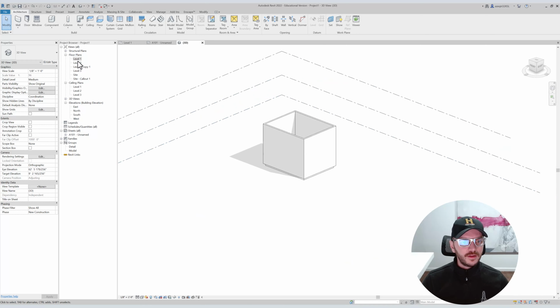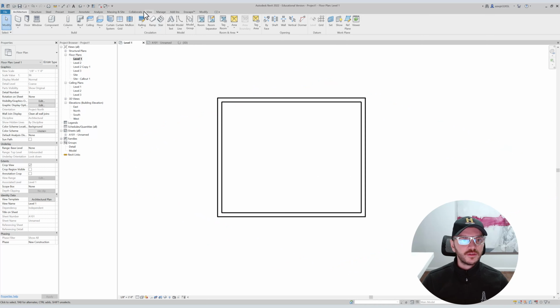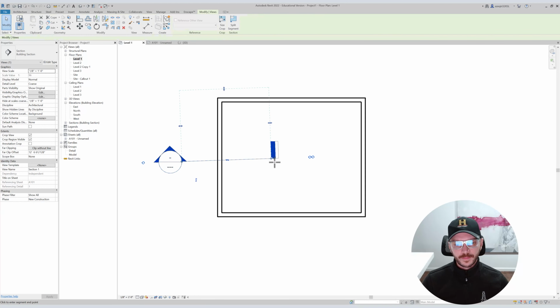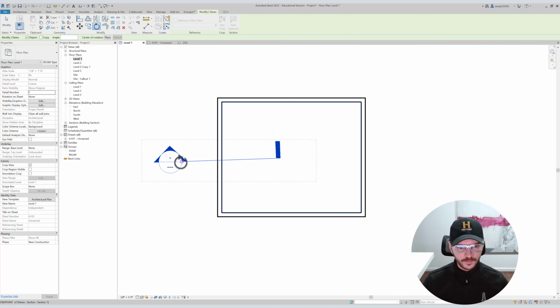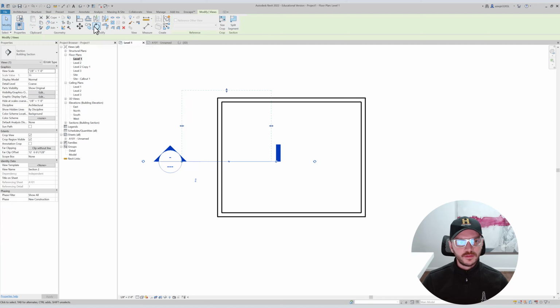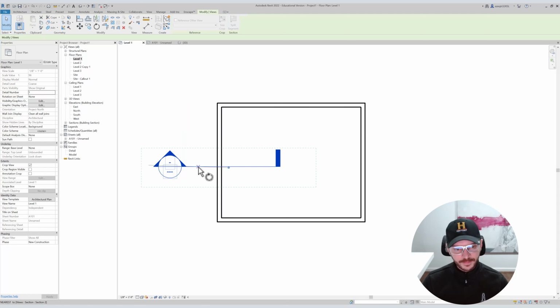All right. Once we're in our floor plan, we can create sections. We can create elevations. Right? So I rotated that using the rotate tool, FYI. If you are rotating something, it will give you the center of axis there. But if you want to change that, you can go here, center of rotation, or you can hit spacebar, and then that's what I do. I hit spacebar, selected those, and then I rotated whichever way I want.